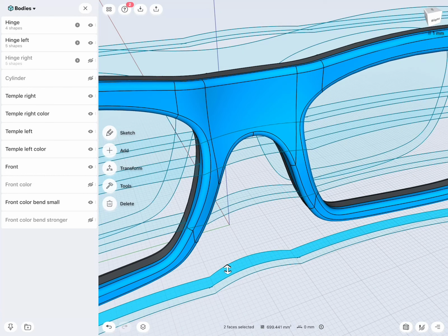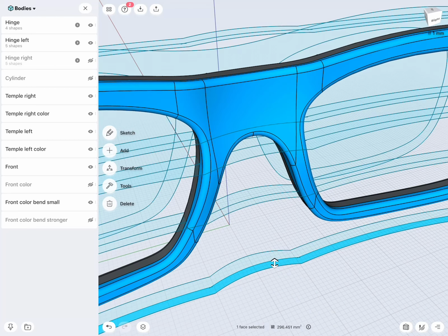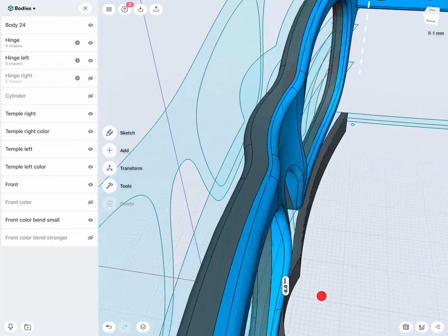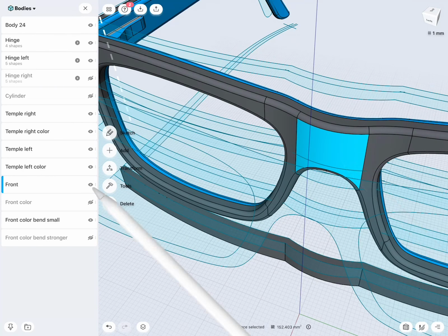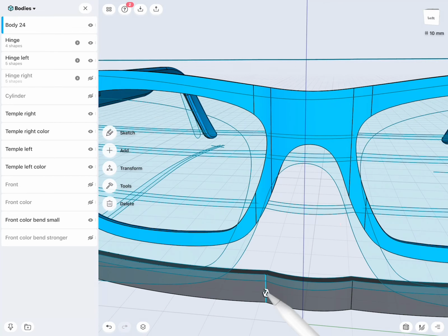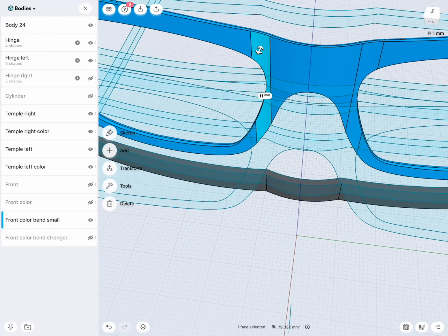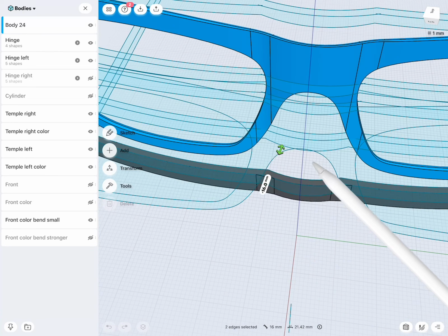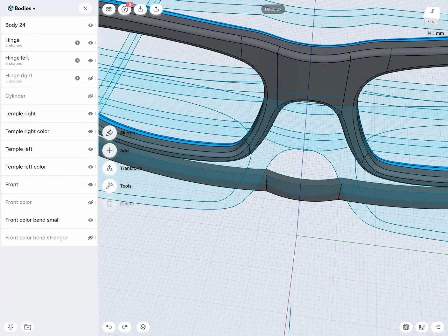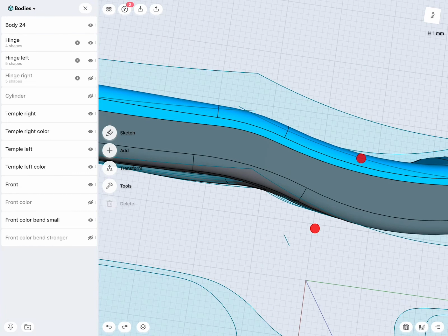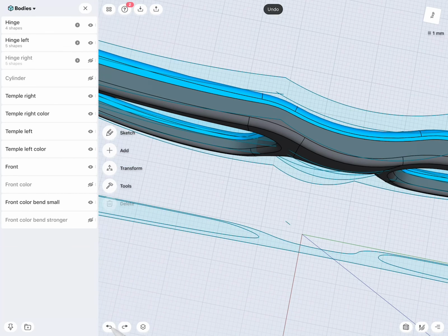I did the same also here. I had the whole frame, I extruded the front part out, cut it, and then I took the full copy of the front frame, and then I cut the back part out. Also here, just as a note, I have a sharp edge here, but here I have a fillet. When I click it, it tells me it's 11 millimeters, so these two edges I simply need to fillet to 11, and then if I run this up, I get exactly the fitting, as you can see, the black and the blue part completely touch each other.